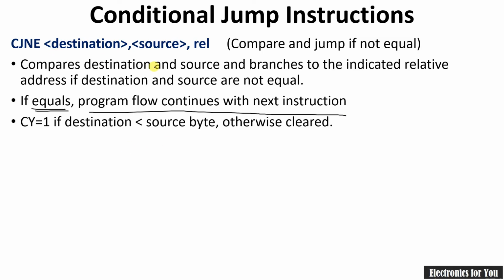This instruction is again important whenever we have to find the largest or smallest number, or arrange numbers in ascending or descending order. It not only compares and jumps to a particular location, but also indicates the larger and smaller value. If the destination byte is less than the source byte, the carry flag will be set.